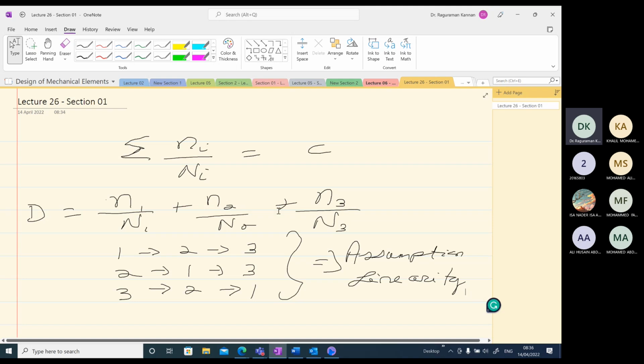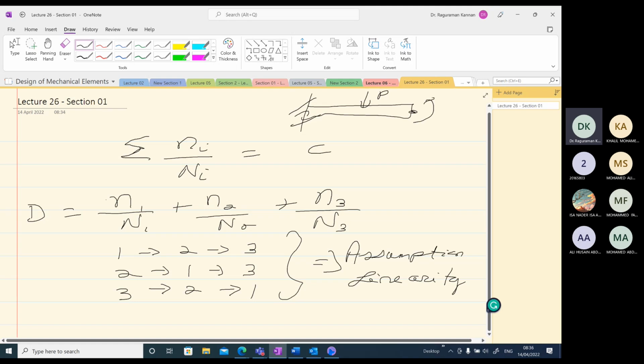For example, if I apply a load P on a cantilever beam and a moment M, I can split it into 2 different problems, one consisting of load P only, plus another consisting of moment only, and then add up the solutions together to get my final solution.